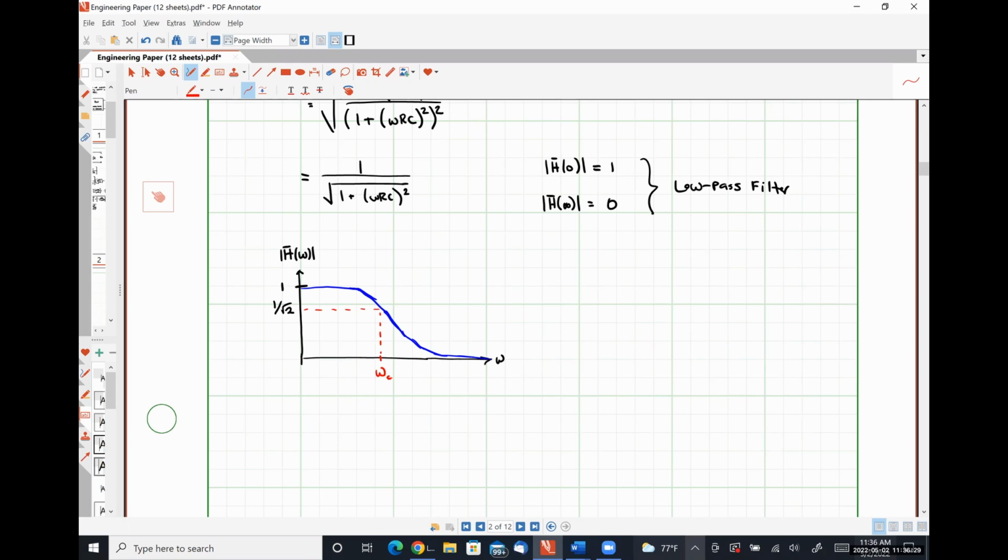Now, this is a plot of effectively how our signal voltage behaves, because it's a ratio of volts per volt. Signal power is proportional to volts squared, which means 1 over square root of 2 squared is 1/2. So that's why we're looking at this point in particular. It's what tells us on the voltage span of how this is going to behave, where we are rejecting or attenuating exactly half of our signal power.